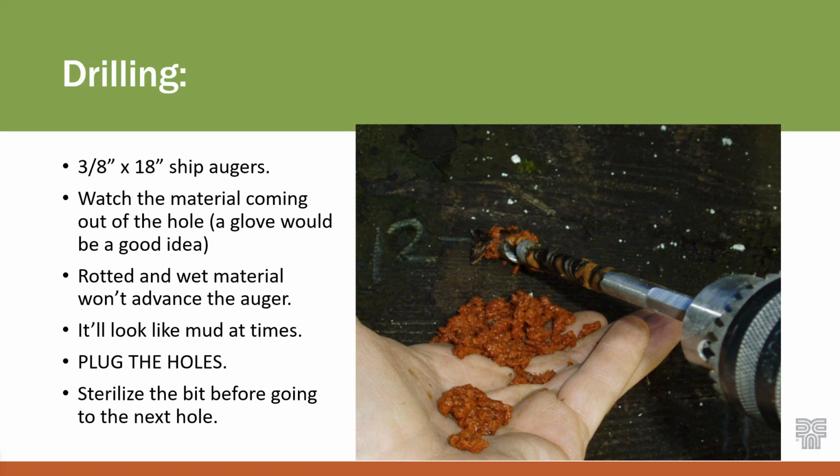Here we've got an example with just their hand using it. You've got a lot of chemicals in that wood from the preservative treatments that aren't usually very friendly, so I would suggest wearing a glove. I would also suggest that as you're drilling these to find the rot, you're leaving 3/8 inch holes behind, which, if you didn't find rot, means you now have a nice avenue to the middle of the timber, where it's not protected, for rot to start occurring.